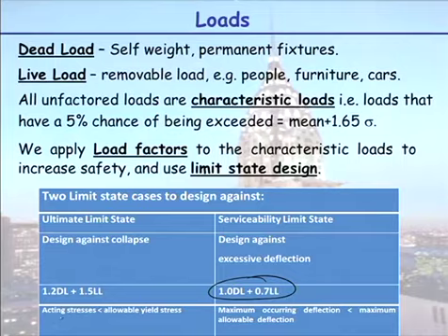This one here, we check our stresses are less than the allowable stress. Over for serviceability limit state, we actually physically calculate how much something deflects, and we ensure it's less than a maximum deflection. So there are two completely separate independent checks we do.